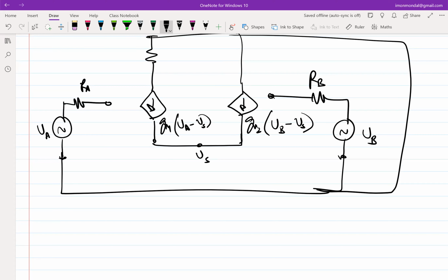So now, let's look at the first issue. The first issue is our transistor GM1 is not loading VB. So that issue is solved. But next the question is, is VS equal to VB? That's what we wanted. So how should I know what VS is in terms of VB? I can find the KCL at the node VS, and then figure out what is the impact of loading in this. So solve for KCL at VS, and let's see what we get.